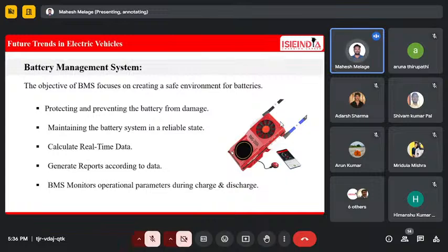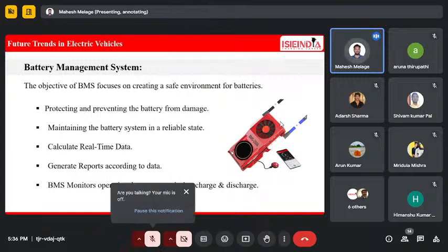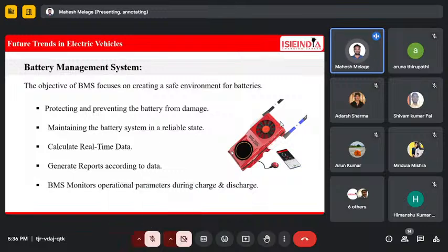And what is the range of the temperature? The battery performs well between 15 degrees Celsius and 35 degrees Celsius. Above the maximum temperature of 35, the battery parameters can be affected, and the chemistry of the battery can be affected also. Simultaneously, the performance will be poor, and the vehicle can perform approximately under specific ratings.